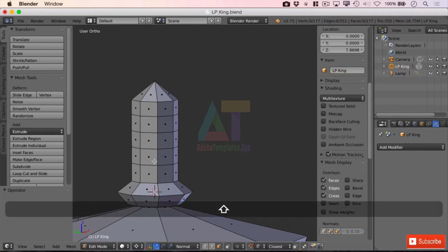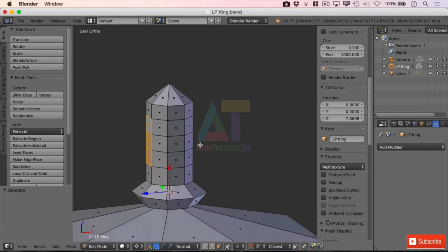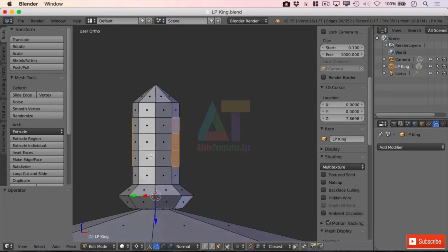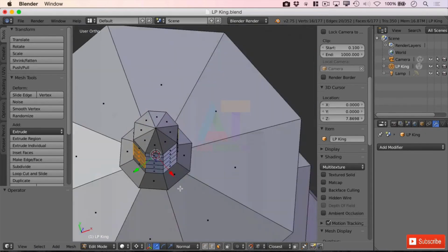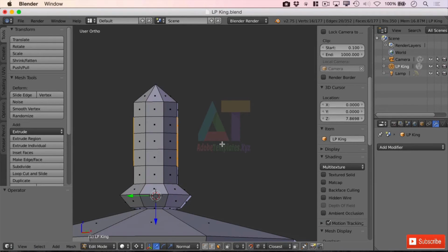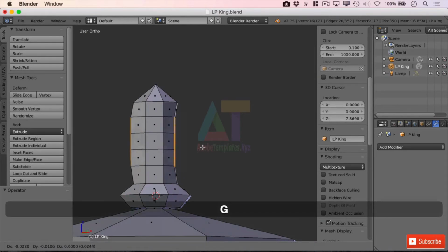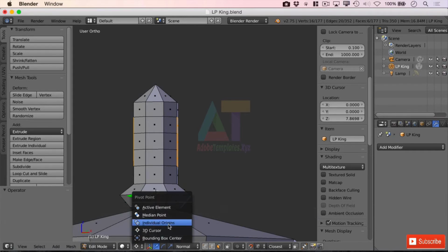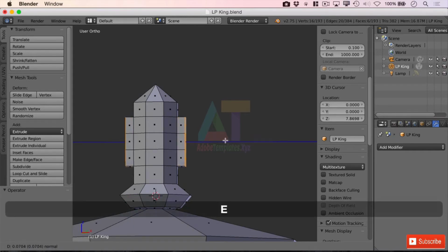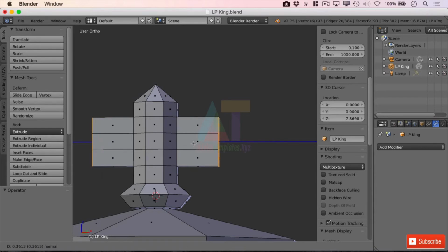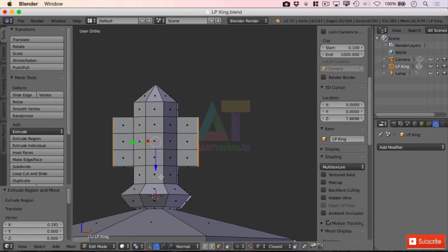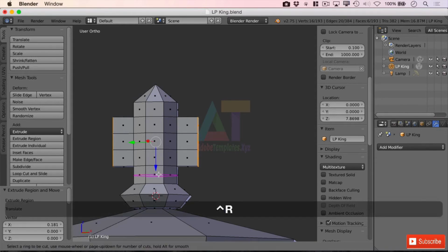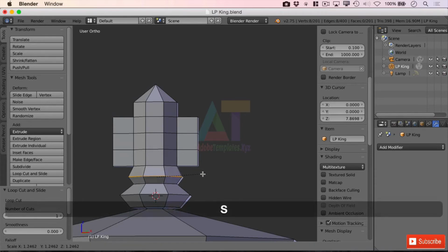So let's select this face here and these faces here. They are opposite one another. Yes, they are. And let's just grab them and pull them about. Well, we need to change the pivot points, not around there, but these individual origins. Then I'll be able to pull that area out, which is perfect. I don't want to do it too far. Excellent. Now, we're going to have to add another edge loop in around here and scale that out.